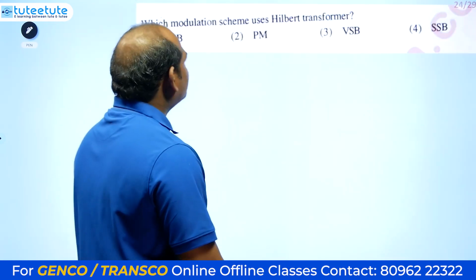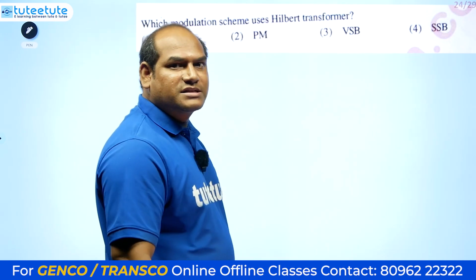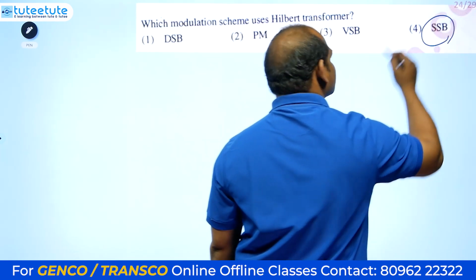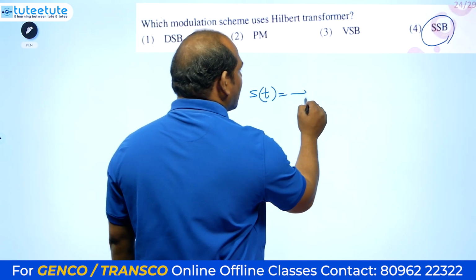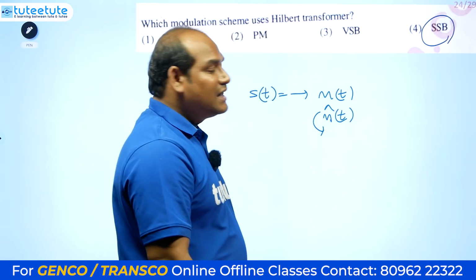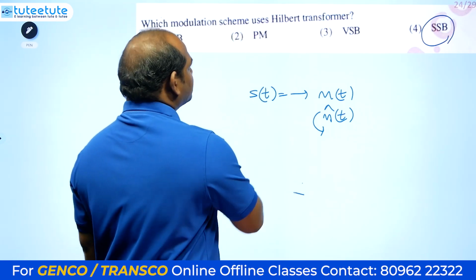Next one is related to the Hilbert transform. If you see all the modulation techniques in analog communication, this SSB equation involves the Hilbert transform. Here s of t is equal to an equation in terms of m of t and m cap of t also. This m cap of t is the Hilbert transform of m of t. It will provide a 90 degrees phase shift. So the answer is simply SSB.